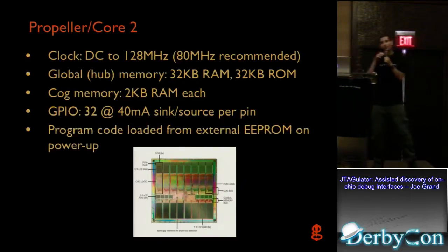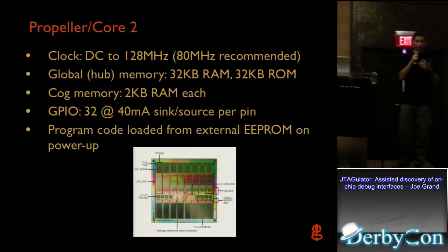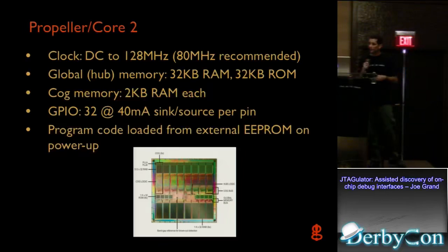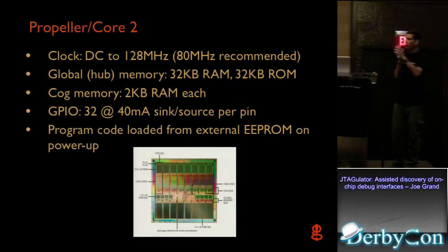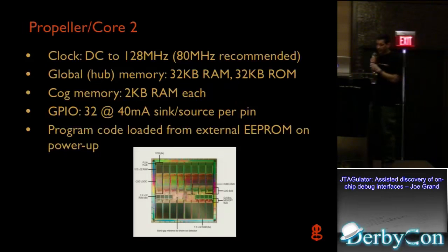A little bit of a learning curve to learn Spin if you haven't worked with it. I guess it's almost like a much higher level language than anybody that's worked with electronics normally is used to. But it's pretty cool, and it's a very powerful part. Normally it's running at 80 megahertz, and it has some individual memory for each cog. You can think of a cog as like an individual core, and everything is sort of running in time slice. You can share I/O pins and stuff. But you can build on the Jtagulator and have tons of functionality because I'm hardly using any resources, which is cool.